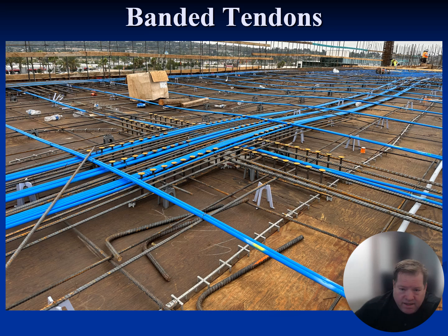And also from a load path point of view, if you're standing right there in the deck, it's easy to see that part of your weight goes to this band, part of your weight goes to this, drops it off to the bands, and then the bands take it there and there. Now, obviously, that's a simplistic point of view, but in relation to a rebar system where you just have all this rebar all over the place and the load path is somewhat subjective, this, from an ultimate strength perspective, holds up the weight, drops it to the band here, drops it to the band there, and then these bands or girder lines take it to the columns, and that's your load path.